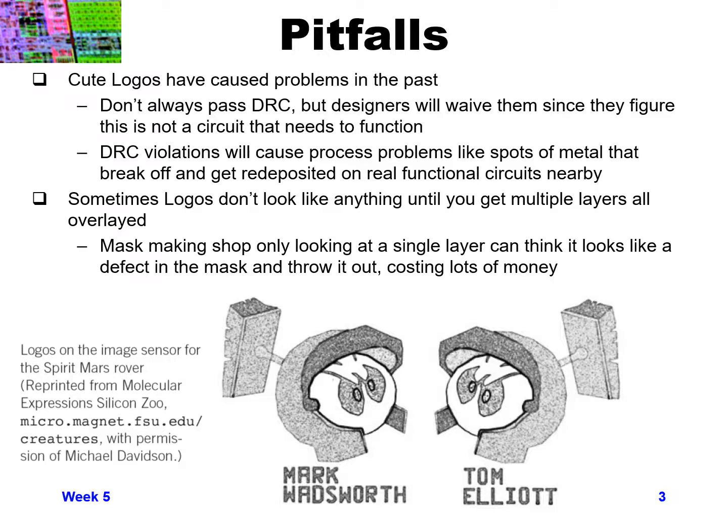So you wind up stopping your etch at a certain spot, but you really haven't etched everything because you had a chunk of metal deposited in a region where it wasn't supposed to be. And so it could eventually cause real functional problems to other circuits that might be nearby, even though this isn't in an area where you have something that you expect to work.